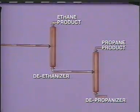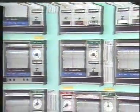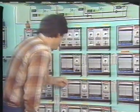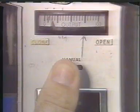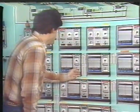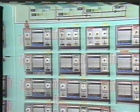When an operator is controlling a series of towers with conventional instrumentation, he must balance out the specification requirements for a number of different products. In some instances, he may have to temporarily relax specifications on one product to avoid changing the composition of a more valuable product. During a process upset, it becomes especially difficult to maintain product specifications because an operator has to simultaneously make adjustments to several towers.